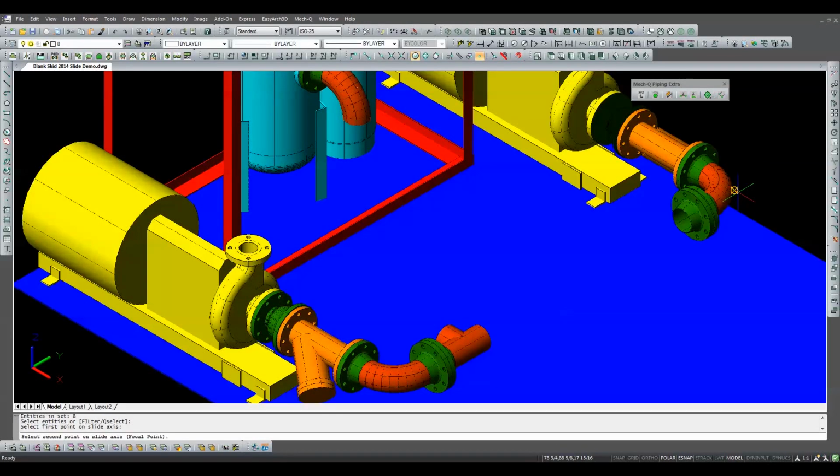The next point picked is, and must be, the focal point of the T. The 3rd point we'll pick will be the center of the end of the T's branch. Finally we'll need to pick the point to align with. This point could be the center of the diffuser tank, the center of the weld neck flange, or the face of the elbow, since their centers all fall along an imaginary alignment plane represented by this gray screen.